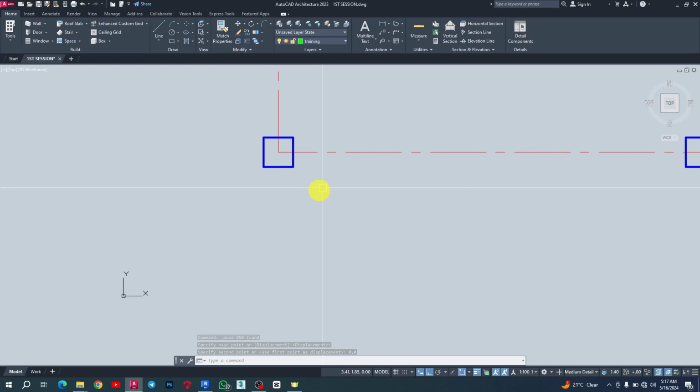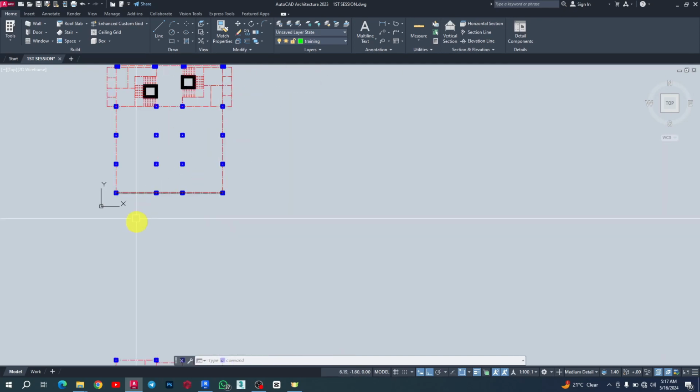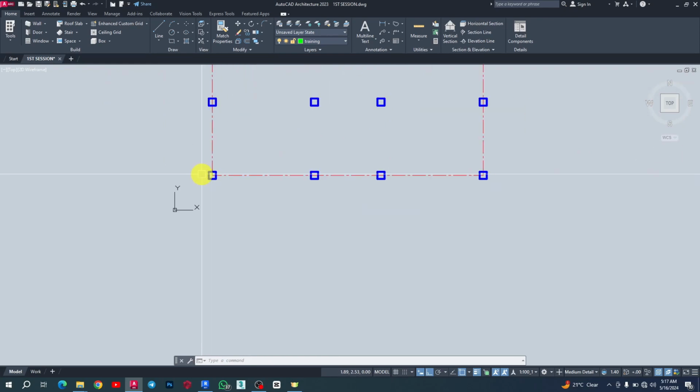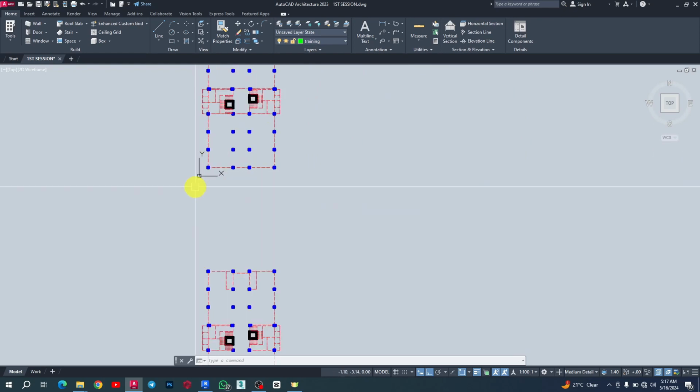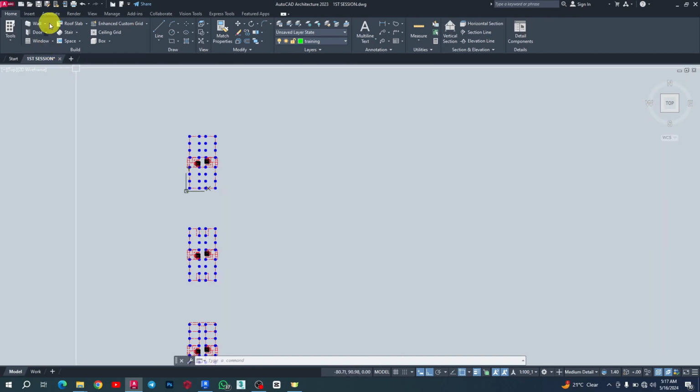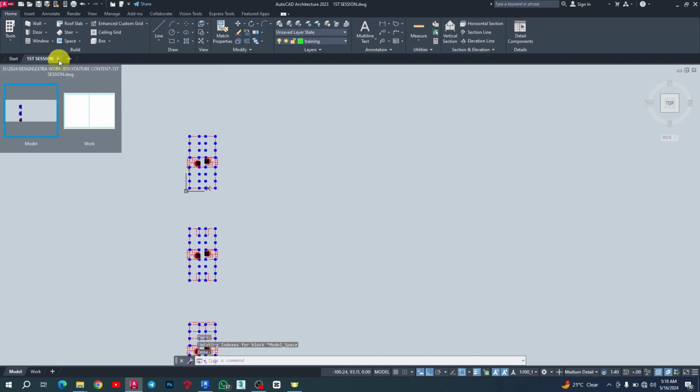So you see it's so close to it, right? So this is what you want to do, so that when you export your drawing, it actually fits closer to 0,0. It will be 0,0 in Revit. Okay, it will be 0,0 for you to work with. So you want to do that before you export, so that your drawing is not hanging somewhere in space.